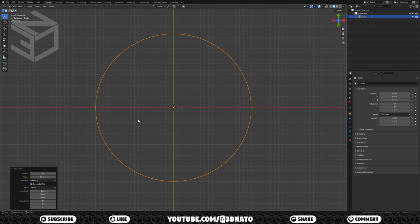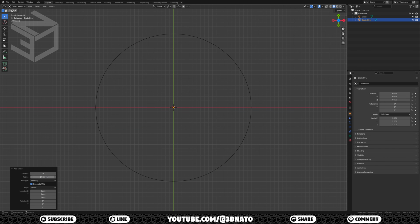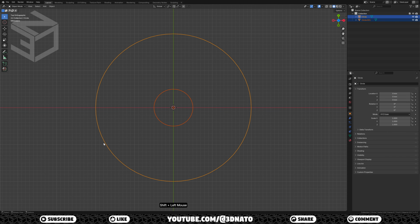As these two circles share the same position, let's add the second one. Press Shift+A, create a mesh circle and set the radius to 5mm. Now let's join them into a single mesh. Shift-select the 20mm radius circle and press Ctrl+J to join them. Let's move it into place.